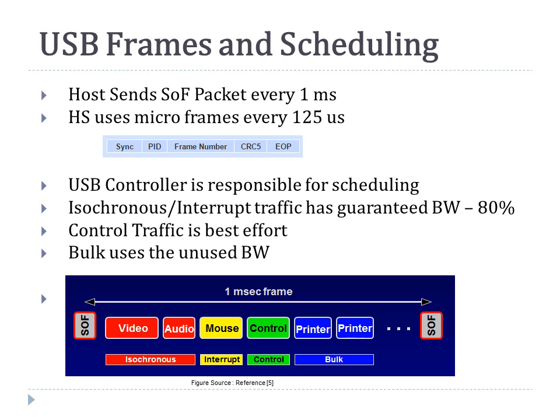Another important concept in USB is the scheduling and USB frames. The USB host sends SOF packet every 1 millisecond. So all transfers are divided into frames, and in the high speed and super speed we use microframes, which is 125 microseconds. Now each frame is divided into different kinds of transfers, as we have discussed: isochronous, interrupt, control, and bulk. So isochronous are more real time, has priority and pre-negotiated bandwidth. So first the frame is filled up with the isochronous transfers, which is the video and the audio transfers, and then interrupt transfers, which also we discussed, which is like polling a device at a certain interval, which is also important and requires a dedicated bandwidth.